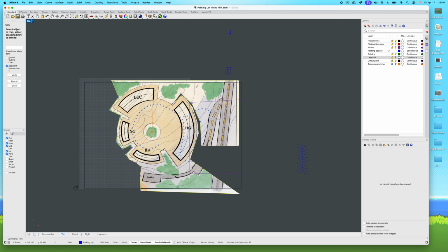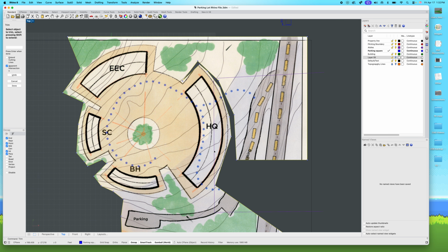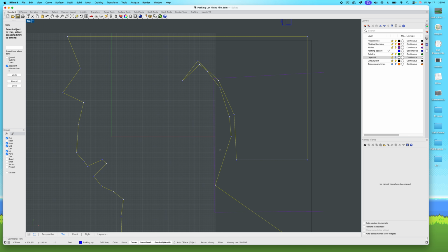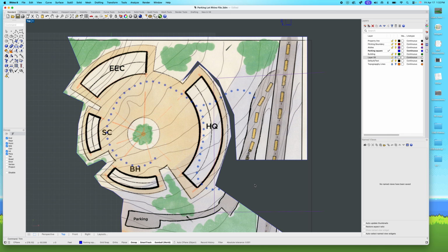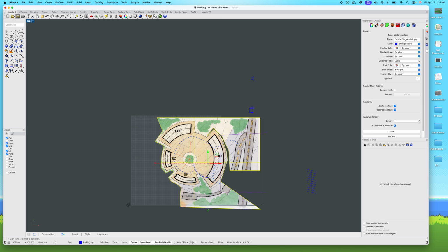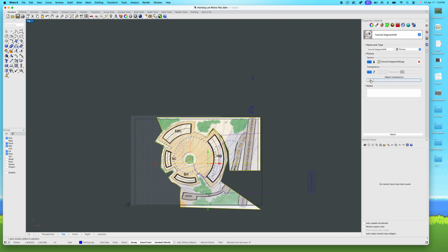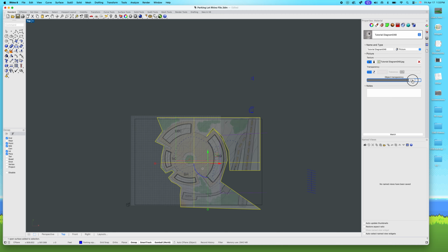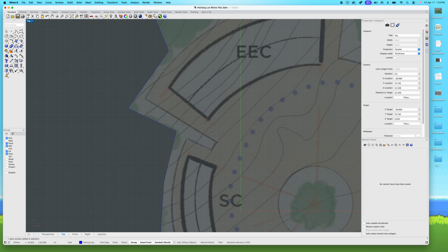But let's say that's what I actually did want to keep. Let's start drawing it. Well, I don't want to trim it out. So again, I can't mess up. Command Z. In my case, I do want to lock that in place, but not before I give it some transparency. So again, I'm going to go to Properties, my little paint tube, and give it plenty of transparency. More often than not, I don't actually need that much of the color, and I really appreciate seeing the grid behind it.